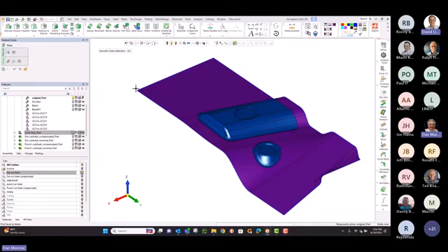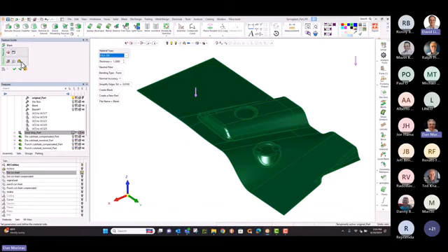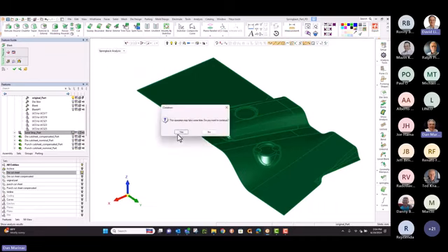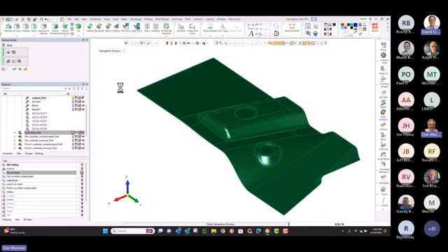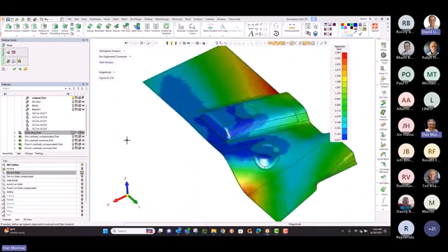Using our blank function, we're going to be able to do our calculations for the wrinkling, the thinning, and also the springback. Under material type, you saw a type of material that was listed, so there's an extensive library of different materials already in the system, and we're just going to have it go ahead now and do the calculation for the springback. So this takes a second or two. We're assuming no conditions on this where we're trying to hold it or anything like that. This is just a quick look at what we might see for springback.